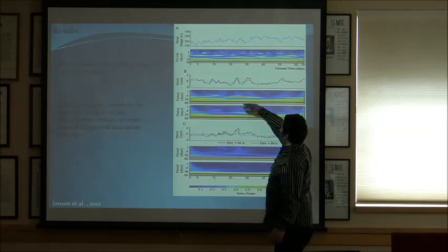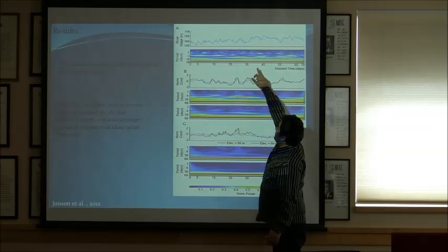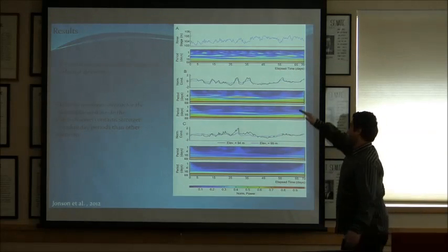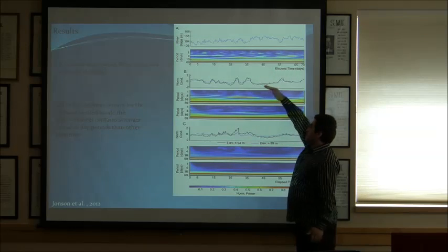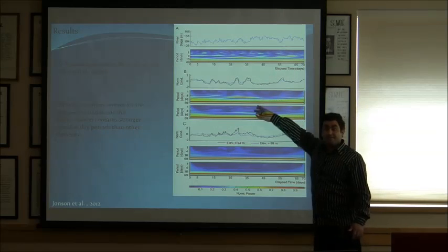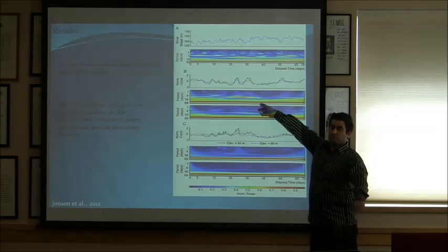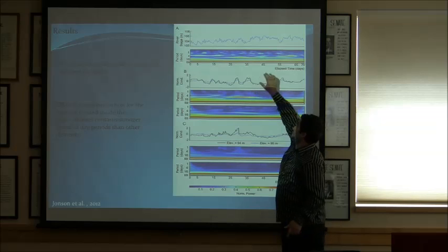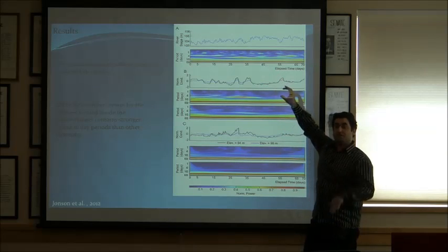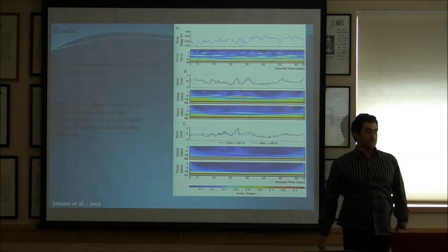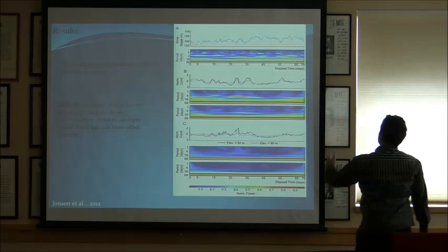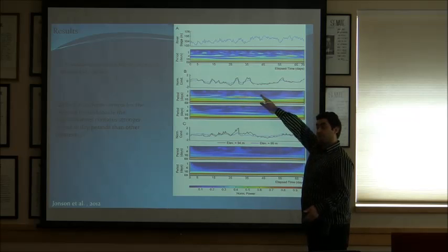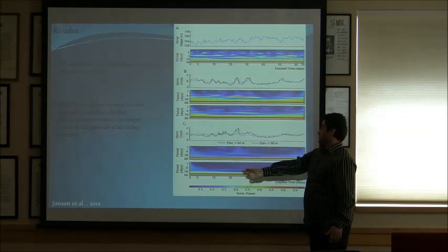So if you notice here, you have a period of 4 that's in the stage, but not here. That tells you the stage variation drives the resistivity variation at this element underneath the 3D array, which gives you a connection at this area between the river stage variation and resistivity variation. So by just this plot, we confirm that at this location there's a valley channel, because you see the same period, but you don't see it here.